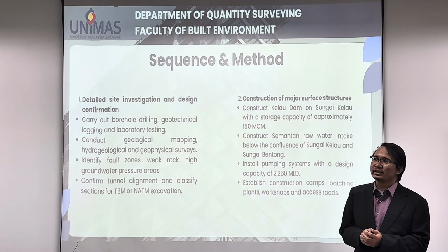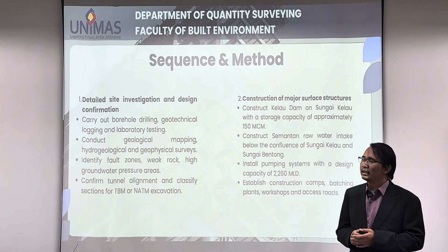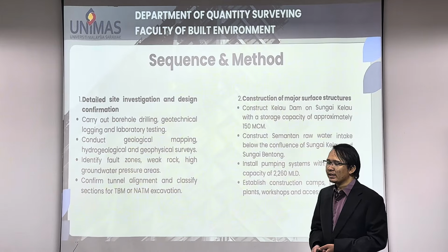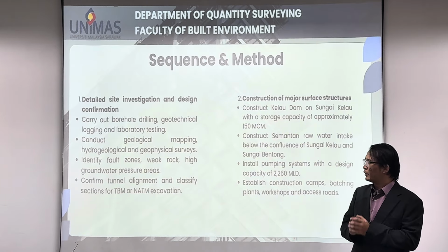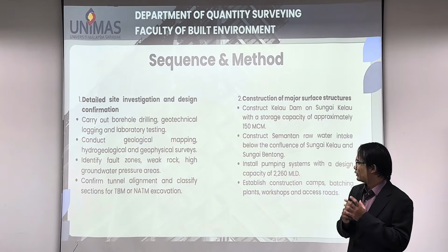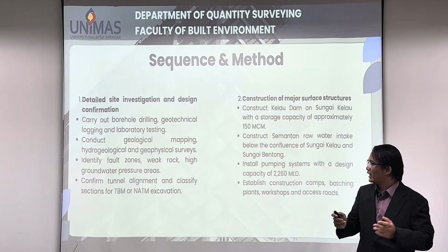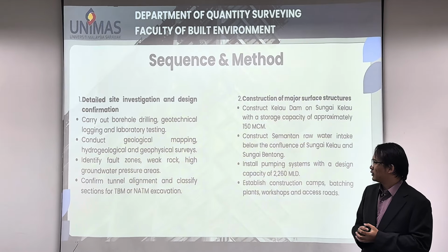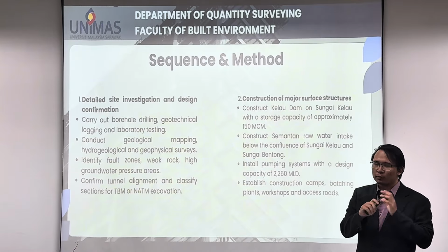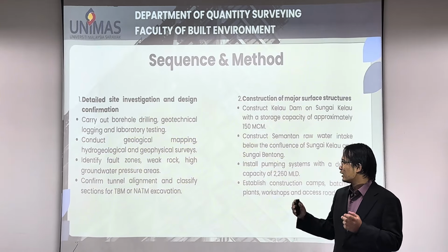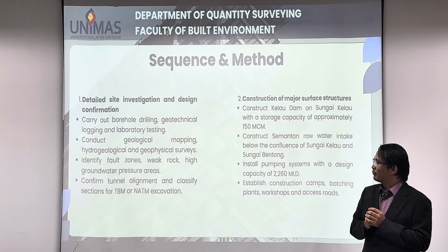Next, the detailed sequence starts with the detailed site investigation and design confirmation. It is to carry out borehole drilling, geotechnical logging, and laboratory testing. It is also to conduct geological mapping, hydrogeological, and geophysical surveys. It is also used to identify the fault zones, weak rock, and high groundwater pressure areas. In this sequence, it is also to confirm the tunnel alignment and classification of sections for TBM or NATM excavation.